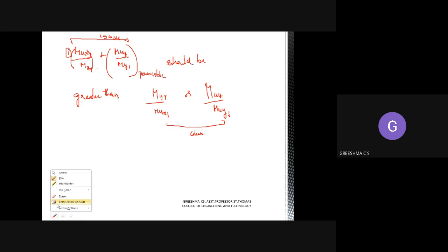First of all, let's see how to find out the permissible value. For that again we have to refer SP16 chart 64, and you also need one ratio, that is the ratio between Pu and Puz. So Pu is how much? 2000 kilonewton, right? 2000 kilonewton divided by 3750. So approximately you will get this value as 0.53.